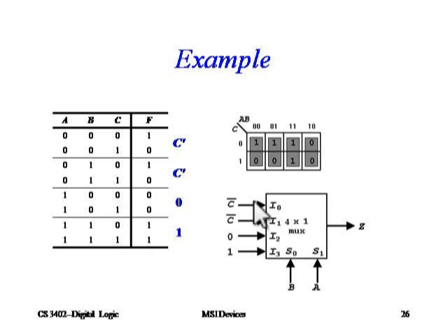So instead of using an 8 cross 1 mux, I can use a 4 cross 1 mux, where the third selection is given as a data. So C bar, 0 and 1. So this is how I can get an output. So this is how we can implement any given combinational circuit using a multiplexer.